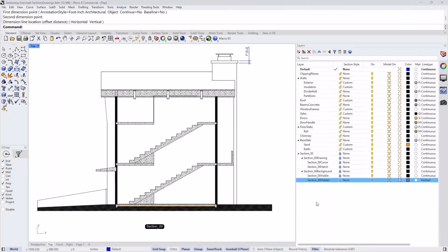Hi, Roger. So even with history, the dimensions will not update as you change the sections. Correct. Because what you're getting is you're extracting drawings, you're extracting projections. Unless we correlate that dimension point from the model down to the drawing, we cannot have that chain. And if you radically change your clipping plane or rotate it, you're really going to lose that point. I think it's much easier to associate with history the points on the object itself and the dimension than you do through the drawing.